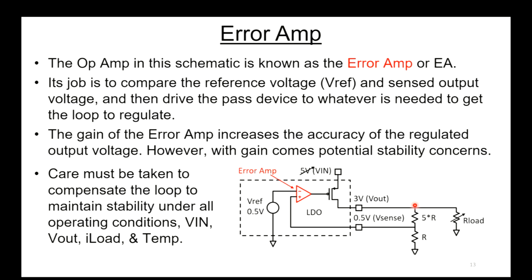But I just want to mention, you have to take a lot of care. You have to make sure that you compensate the loop to maintain stability under all operating conditions: the input voltage, the output load, and temperature.